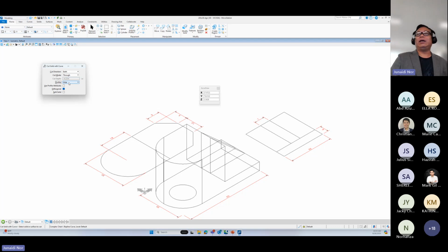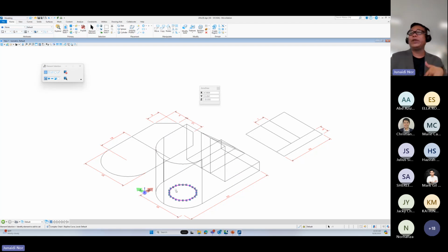So I put hide, I'm confident. Features, both cut through. Select this one and select the circle. Got a problem. Now it cannot cut through, because although you see a circle, this element has not been transformed from MicroStation to become a polygon. So this object is still a raw material, a raw element that came from PDF. So you need to make it smoother.